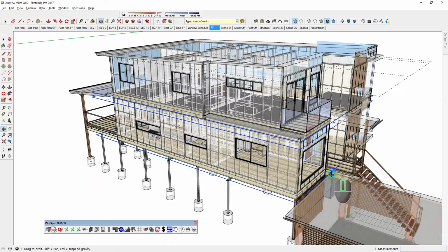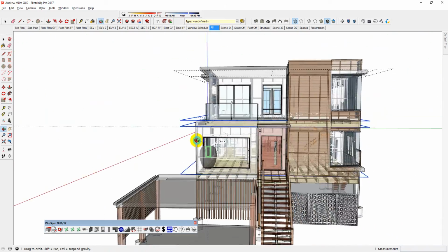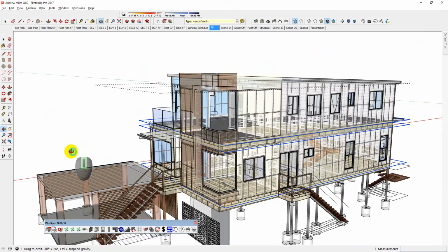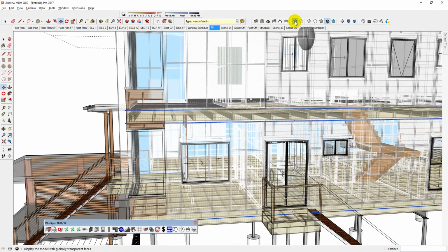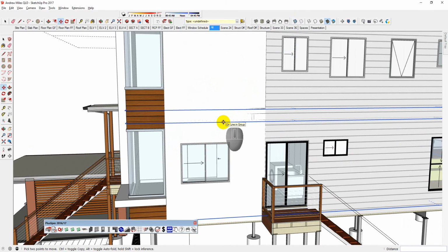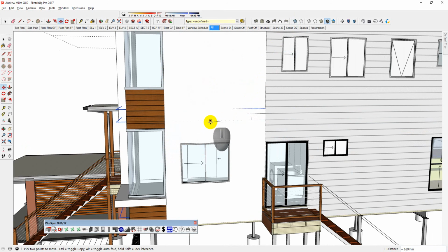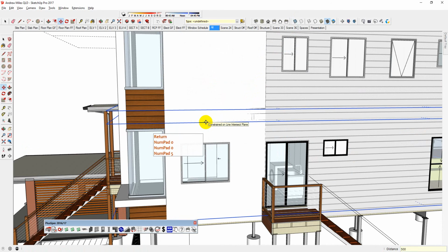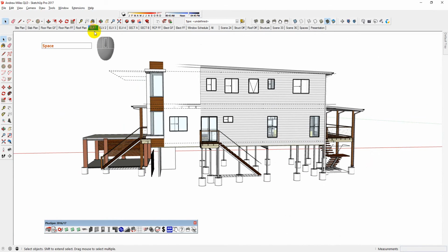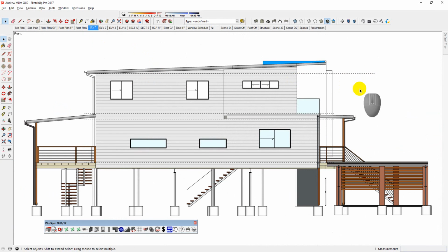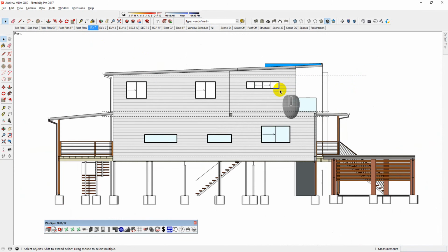Okay, so all I did is I moved it over to the right there so that I can see it in my different elevations, and I might also move them forwards a touch. I always like to try and find the easiest way to do things. I'm looking for an axis. If I use my left or right button, okay, that's green, right arrow, left, and I'm going to say move it 500 millimeters. Enter. Okay. Now I have some dotted lines. If I look at my elevations, you can notice that I can use these to dimension from. Okay, file save,